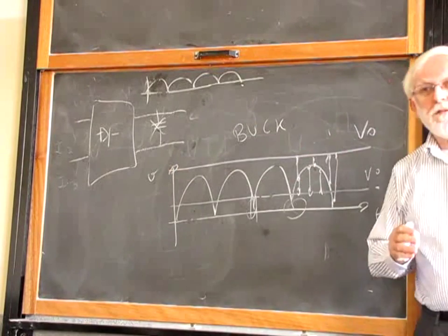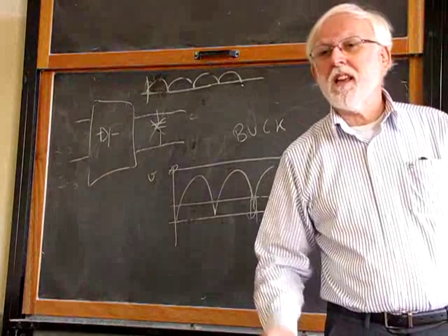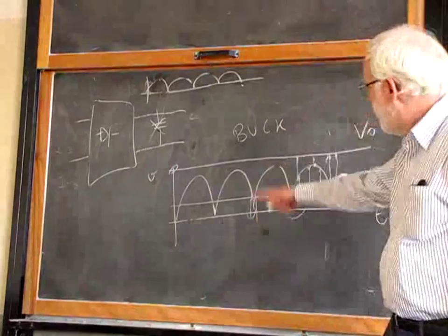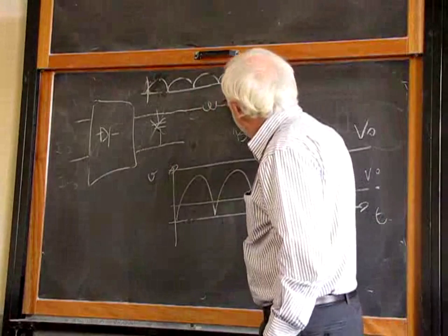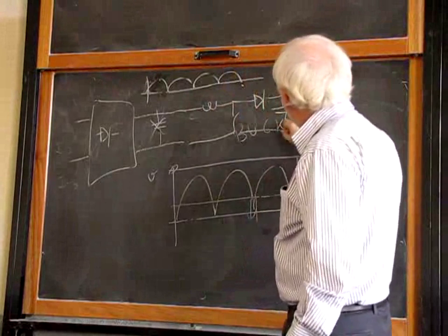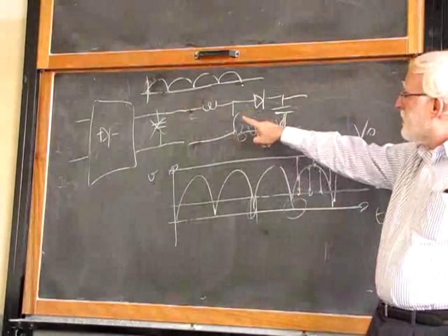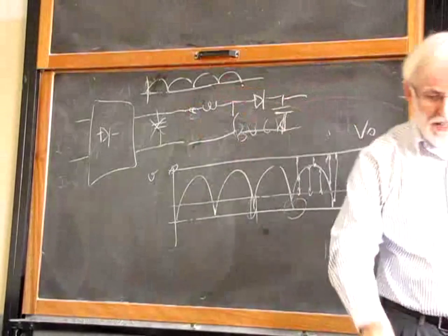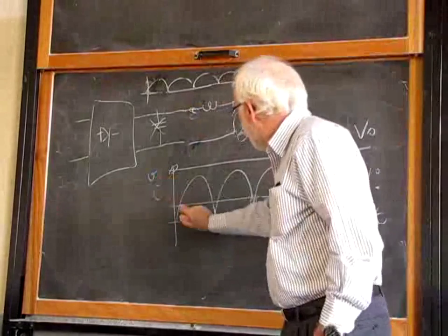And if we are good enough, it's not easy, but it can be done, we can control the boost converter, we can convince the boost converter to send a sinusoidal current, or this kind of sinusoidal waveform. So we put here a boost converter, for example. We measure the voltage over here, and we control the boost converter in order to take an input current that is proportional to the voltage. We can get an input current that is something like this.